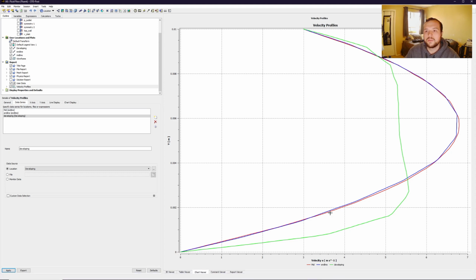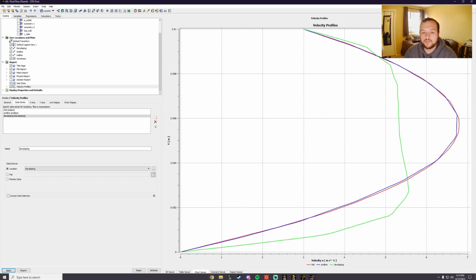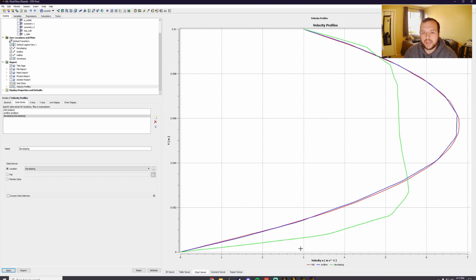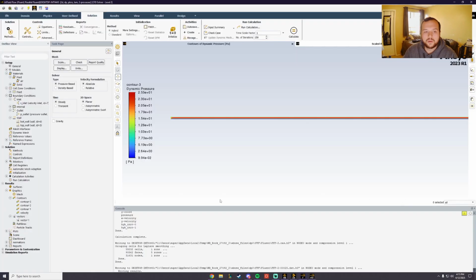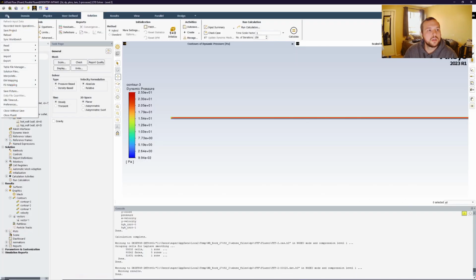Then using all of these results we've gathered, we can move on and find the maximum velocity and the height at which that occurs, either via Blasius or through the data Fluent gives. And then we can determine the pressure gradient out of a report from Fluent. When you export the solution data, there will be a drop down for dpdx, which I will show real quick.